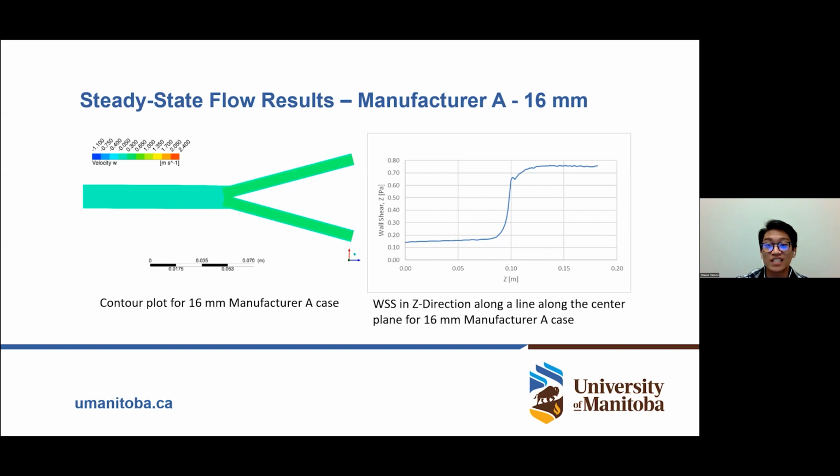At the bifurcation, a slight change in the wall shear stress is observed and plateaus off. The shear stress increases at the bifurcation as the fluid flows through a smaller diameter where the fluid accelerates. Since an increase in the near wall velocity is related through a logarithmic relation to the shear stress, the increase in shear stress is expected.